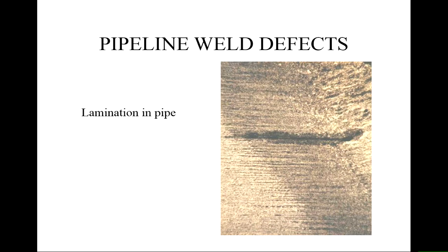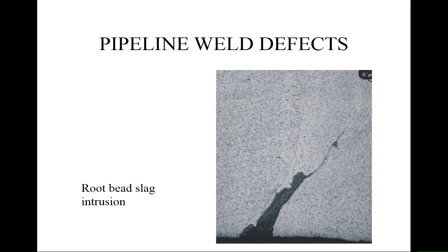And obviously, from this micrograph, judging by the microstructure that we observe, this is the weld pool, this is the weld. This region appears darker, so we know that this is the heat affected zone. So we have a laminated inclusion in the heat affected zone. So it's very likely that this will be an area where delamination will occur. Okay, what else do we have here?